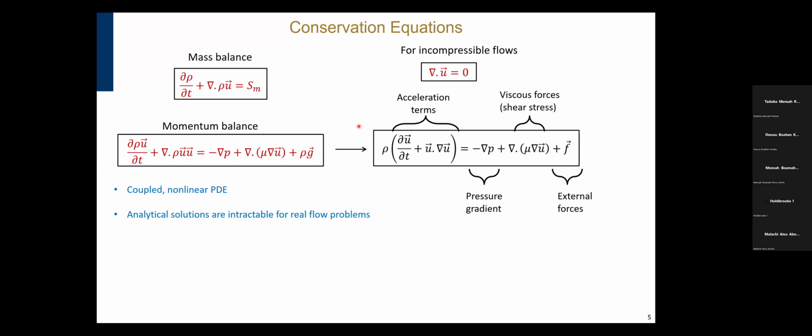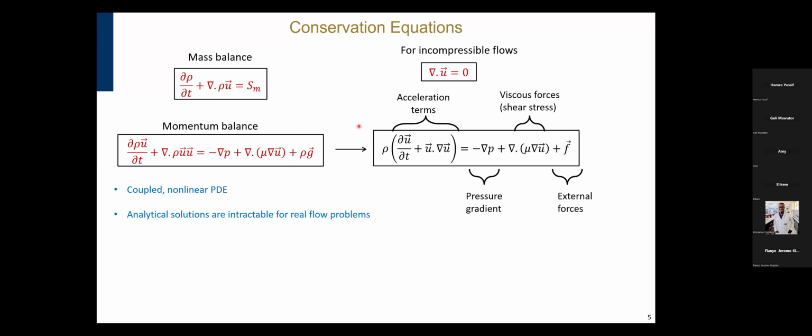So, Dr. Nyadi, if I may add a follow-up question, in undergrad we used to solve questions like falling film and water falling through a pipe. Can we still do that on CFD? The kind of things that we used to derive. Yes, and you would actually be able to do that in much more detail. Think of the fact that for your falling film, for instance, you could end up simplifying this momentum equation, and then you end up with maybe a one-dimensional equation for your domain.